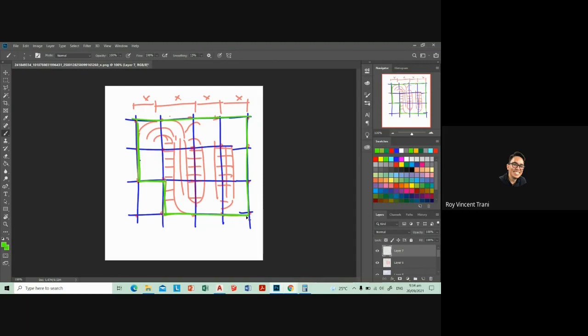And then your upper floor setback. So your columns should follow it. So you need to think about your column layouts. I'll color this a different color. It should hit all your floors, like from basement to top. As much as possible, keep the column spacing regular. So really, this is why I'm telling everyone, I'm sure your comments on Canvas are saying start with the column layout and then you can go to your floor plan.